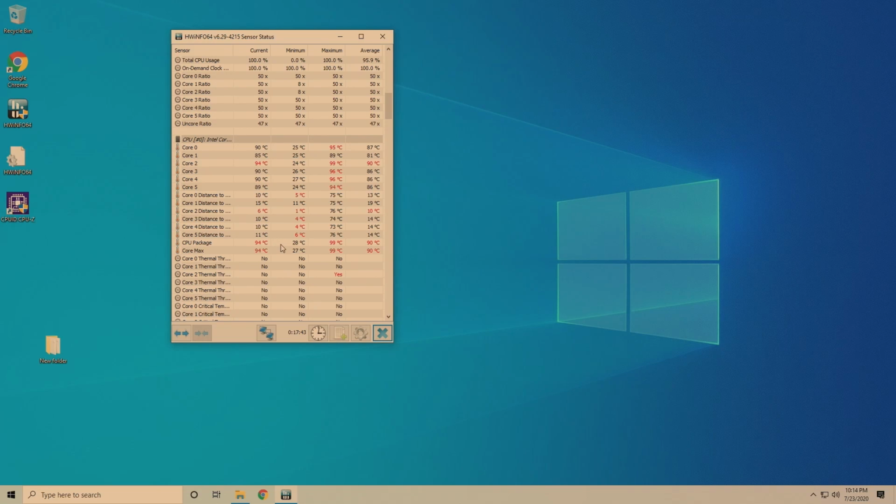We're gonna leave the overclock here at 5 gigahertz. It just doesn't seem worth it to go to 5.1. Seems like we're gonna need a whole lot more voltage just for that extra 100 megahertz, and it's just unnecessary, in my opinion. And one thing that we didn't mention before that I just wanted to add before we end this video is we did run overnight for another 12 hours with AVX enabled, and it was stable.